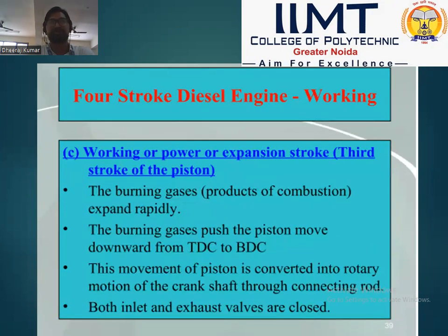Four-stroke diesel engine working. The third stroke is called the working stroke, power stroke, or expansion stroke. The burning gases, the product of combustion, expand rapidly and push the piston downward from TDC to BDC. This movement of the piston is converted into rotary motion of the crankshaft through the connecting rod.